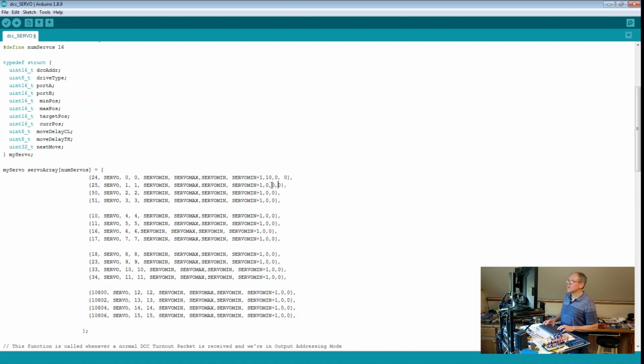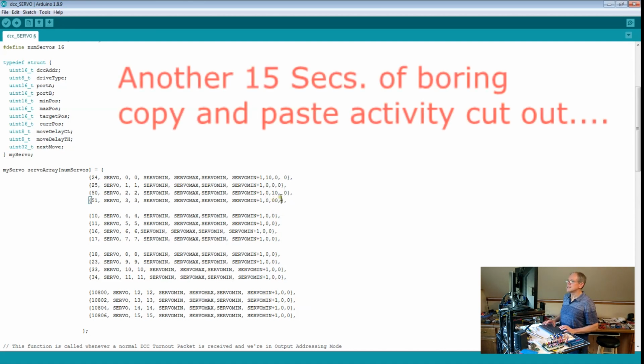I'm just making 2 examples here for the third line, where that's my second servo. As you remember, I only have implemented every other. I do it the other way around, so I give it a 10 as the second timer variable. So that means the first servo should go up slow and fast down, and the second servo should go up fast and slow down. So we will see that. That's basically just for testing, and everything else is getting a 0.